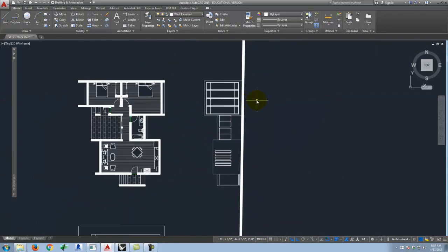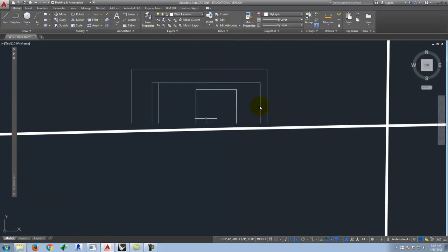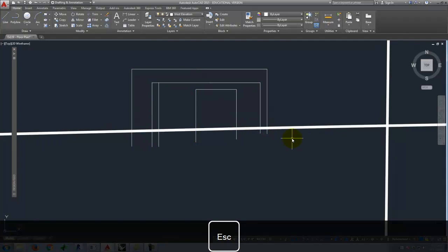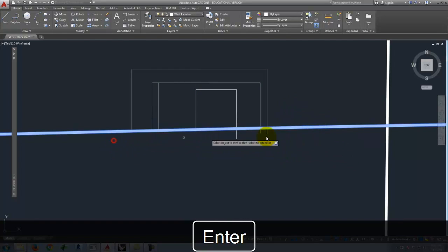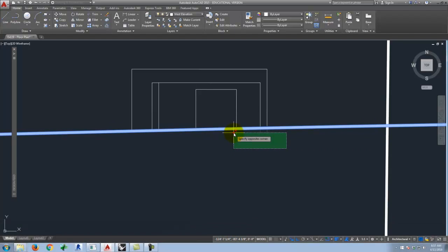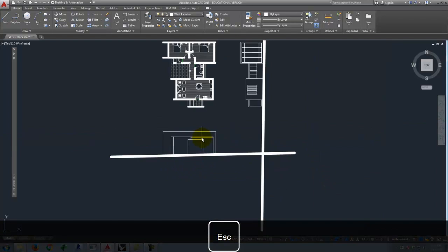And now we can start to see there's one elevation, and here's my next elevation. So I'll do the same thing, where I'll extend all of these below. Like that. And then I can trim all of these off like that, and I end up with that side of the building.